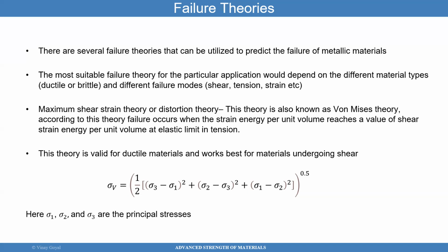Here, the form that I'm presenting is in terms of principal stress. There is a form that's presented in terms of the multi-axial stress states that you've seen before, where you have shear and tension applied. In this scenario, I'm introducing to you one where it's only in terms of principal stress. So if you're given a multi-axial state of stress, where you have shear and directional stress components, you'll have to find the principal stresses first, and then you can use the von Mises theory with the formula I provided here. This is the easiest to memorize, and that's why I like it very much.